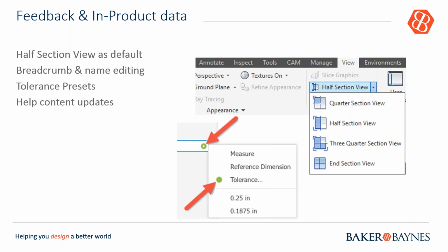As you can see on screen, you can access the tolerance dialog from the field flyout menu to revert to no tolerance value, set the tolerance type to default, and save the preset. When a value has a tolerance, the value edit control displays a colored background under the flyout arrow, as you can see in there, and on the flyout menu itself. All right, so that's some really nice enhancements to it. So these are all productivity enhancements, allows you to become a little more productive when using Inventor for design.